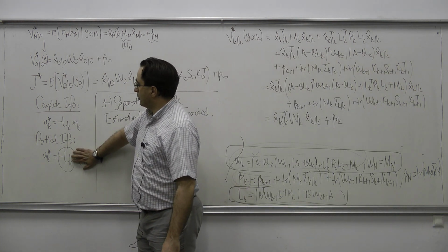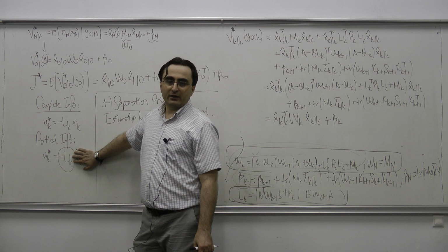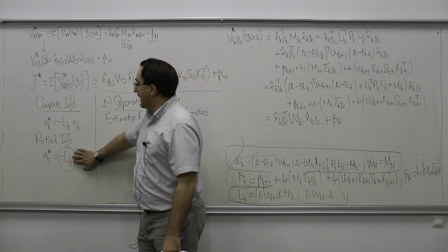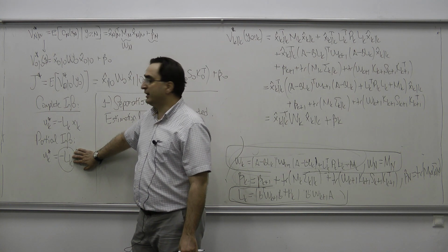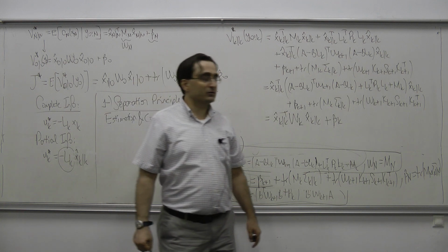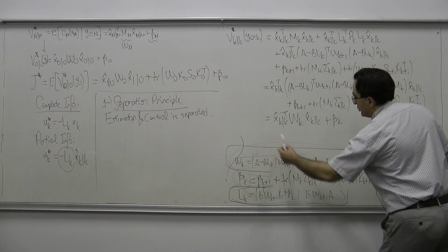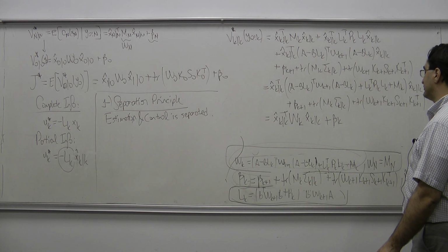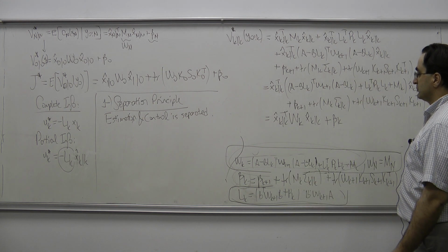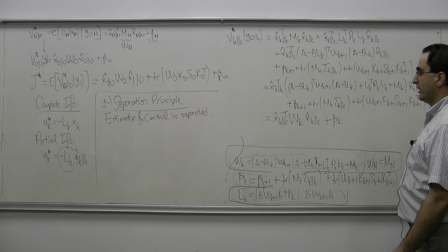The control related quantity is this feedback gain LK, and it does not use any estimated quantities. You see that these W terms here are not dependent on the Kalman filter gains or Kalman filter covariances.